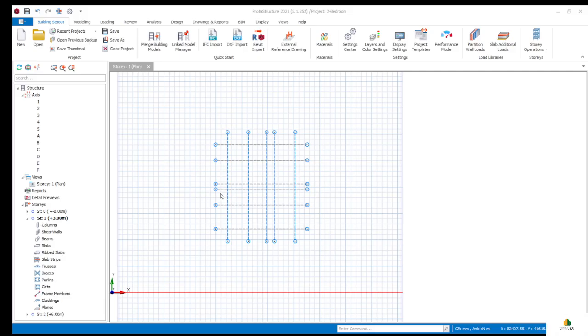Look for similar story, and where the similar story is, you see define selected stories as similar. So what you do is click on define selected stories as similar. The moment you click on that, you see that in the similar stories column, the row for story 1 will change to 2, and the row for story 2 will change to 1.